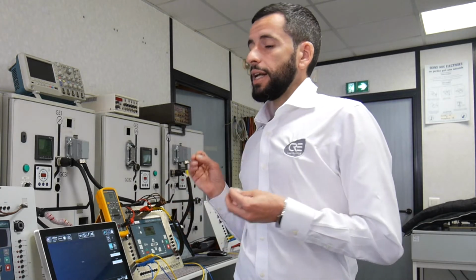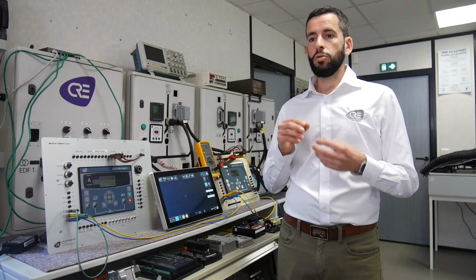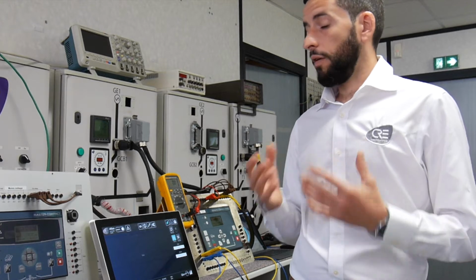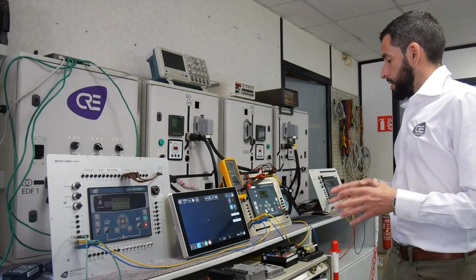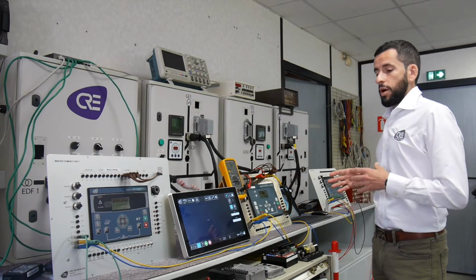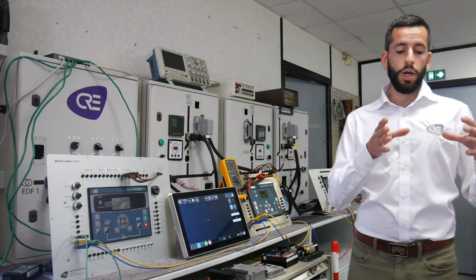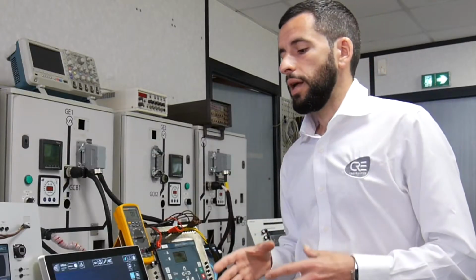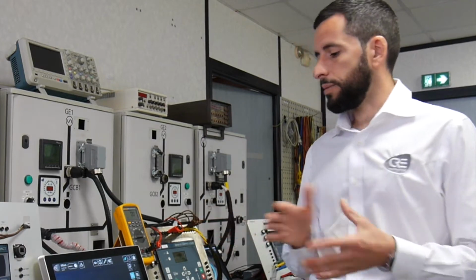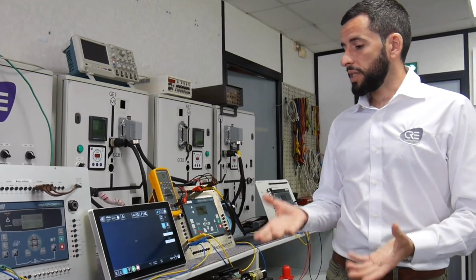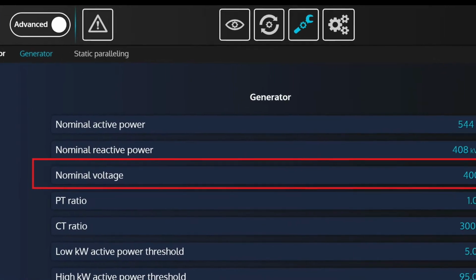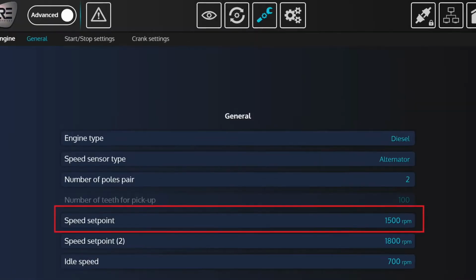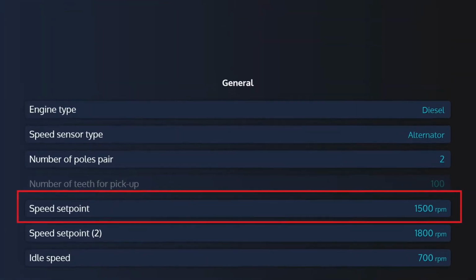So there are ECUs that work with J1939 speed control, or that work with some digital or analog input to raise and lower the speed of the engine. Whatever system you have on your gensets, on your alternator and your engine, it will work fine with EasyCalib.